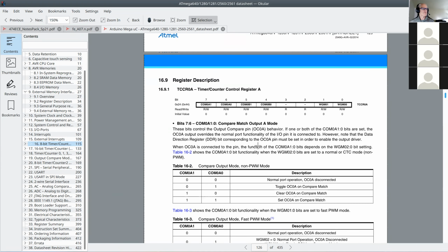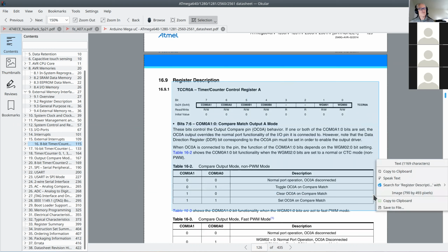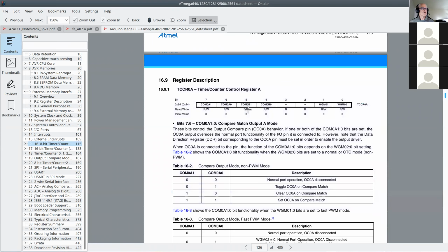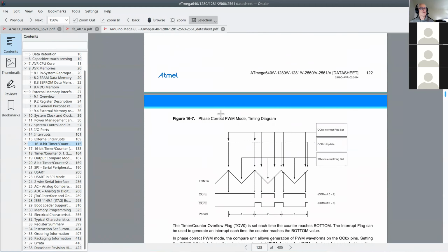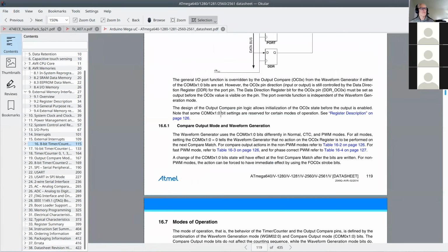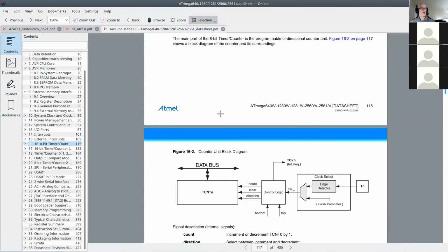And there's timing diagrams, and these are the registers. So I tried to sort of copy this with the pod bay door thing. And so these are the 8 bits, and these are what they mean. And dash means nothing's used there. It shows you this is a read write bit. And then this tells you exactly what those bits do. So here's like for control register A, for output A. So the timer, you've got to keep referring back to this diagram. Way back here.